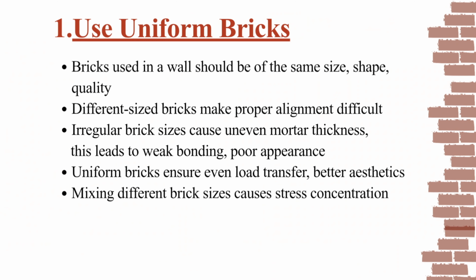Use uniform bricks. Bricks used in a wall should be of the same size, shape, and quality. If bricks vary in dimensions, proper alignment becomes difficult and mortar thickness becomes irregular, and this leads to weak bonding and an uneven-looking wall. Uniform bricks ensure even load transfer and better aesthetics.